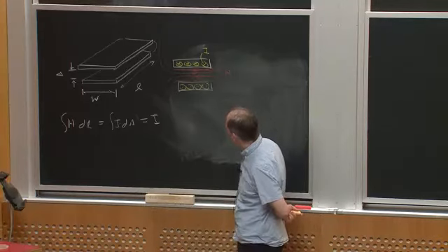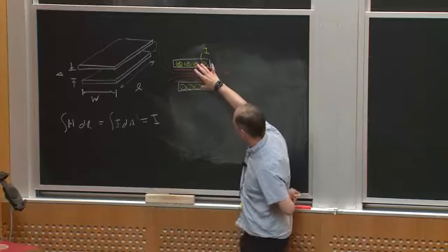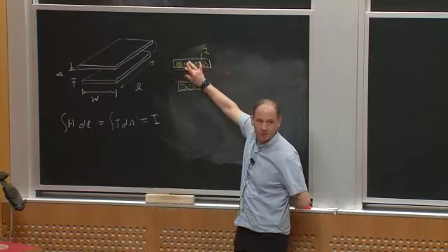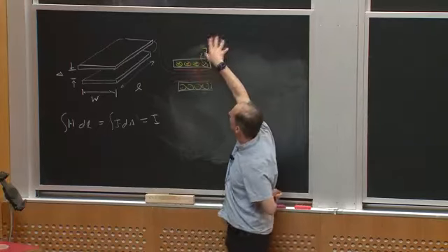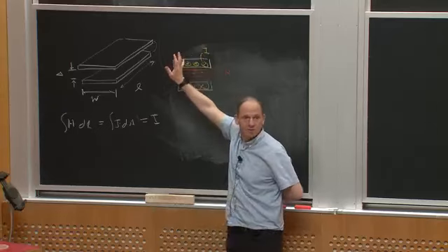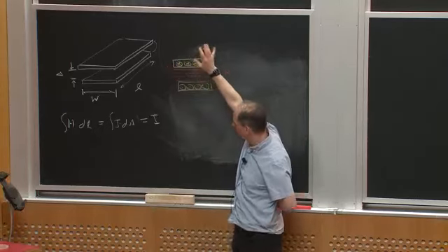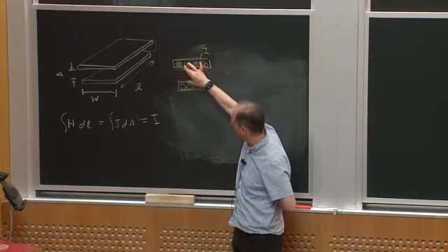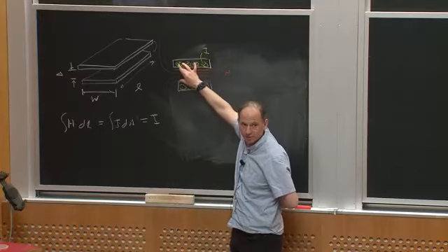The simplest thing for me to think about might be the fact that the fields are really concentrated in between the traces, and they're kind of very diffuse out here. So maybe I can make the approximation, and this is purely approximation, that all the field that I'm interested in is in here, right?